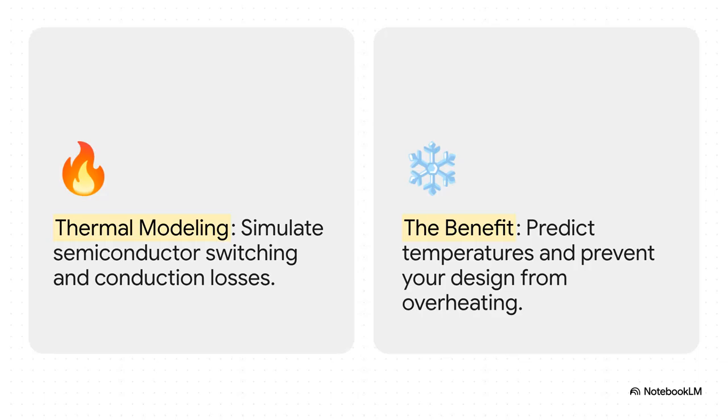Here's a big one: heat. Power electronics gets hot, right? Plex lets you do detailed thermal modeling. You can actually simulate the losses from your semiconductors. And the benefit there is huge. You can literally predict if a part is going to overheat and figure out your cooling strategy before you've even ordered a single physical component.